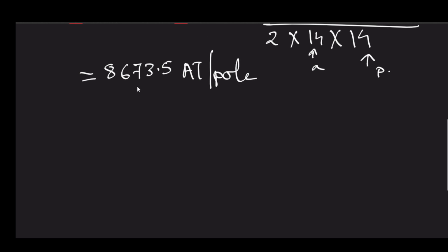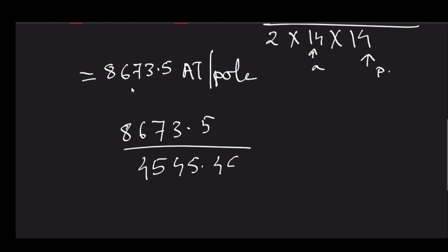So that is equal to compensator winding conductors per pole will be how much? See, this is ampere turn. Now how many conductors do you need to form a turn? That is 2 conductors, and we have to divide it by the current to get the turns, and then if we double it, then we will get the required number of conductors. As per the book calculation, it is coming around 4 conductors per pole.